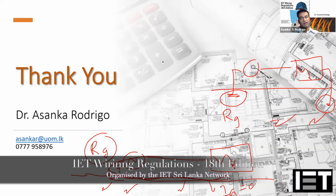But in the other case, without underground, if you are using a normal 4-core cable inside the conduit, even a single insulation failure will not do anything, because you don't have the outer cover or an earthing connection. It is not a sustained earth fault. You have an insulation failure, but you have double insulation and the conduit as well, so if there are two insulation failures, then that will be detected. But that new requirement is there for the underground cables.